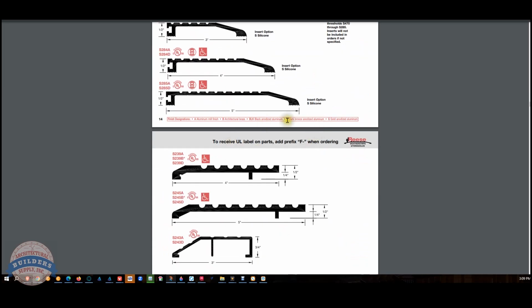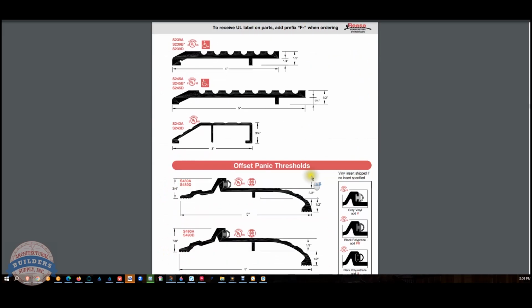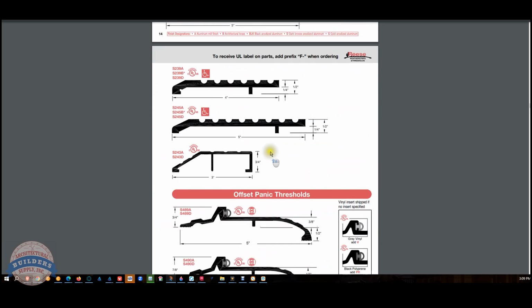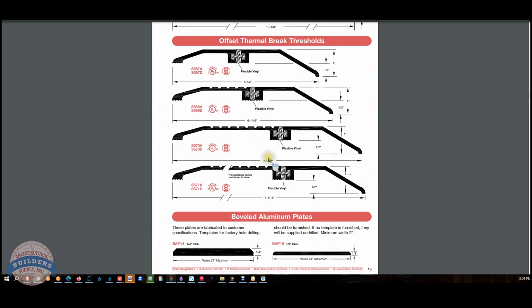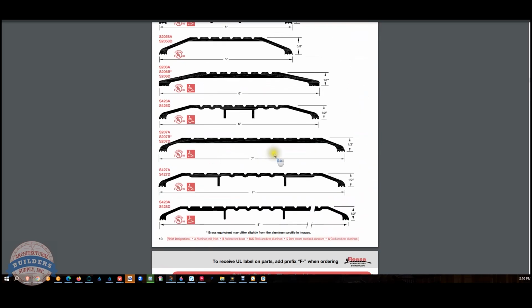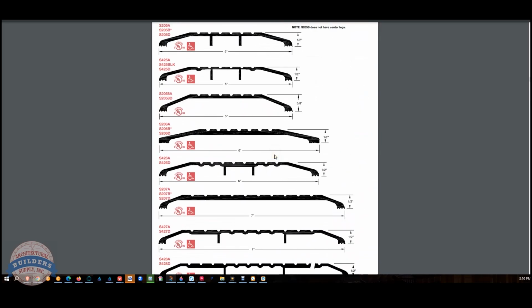The problem is, if we were to take something like this and rip multiple pieces and weld multiple times, in theory it would work, but the requirements that the client has, when they're all brought together, really exceed what a manufacturer can make. However, taking a piece of half-inch thick plate aluminum in a 6061 alloy is something that we can absolutely give them what they want.